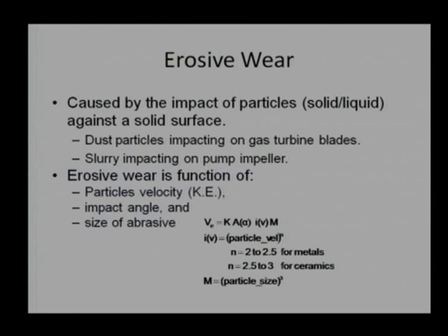Increasing the particle size will increase the wear rate. Increasing the velocity will increase the wear rate, and impact angle will affect it one way or the other, depending on what kind of material we are using. Whether the material has a tendency to absorb the energy or it has hardness to resist the wear. So, the wear rate will be decided by these two properties.